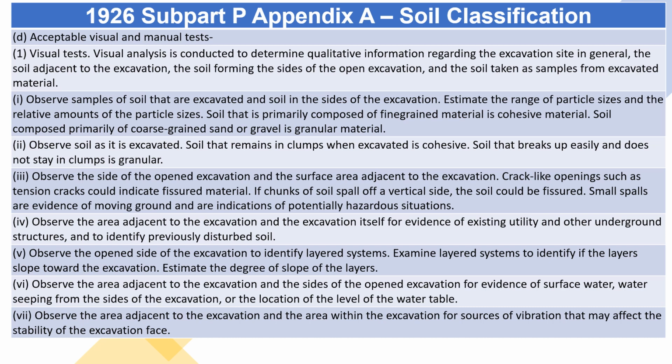6. Observe the area adjacent to the excavation and the sides of the opened excavation for evidence of surface water, water seeping from the sides of the excavation, or the location of the level of the water table. 7. Observe the area adjacent to the excavation and the area within the excavation for sources of vibration that may affect the stability of the excavation face.